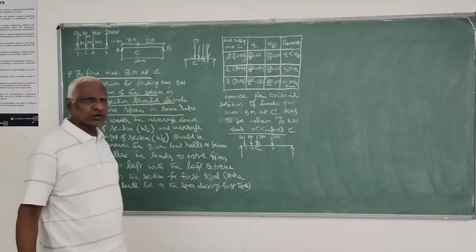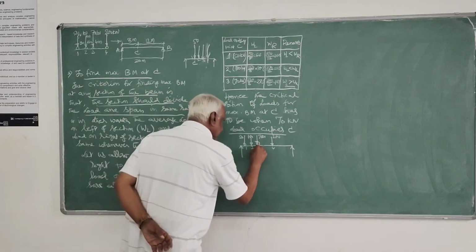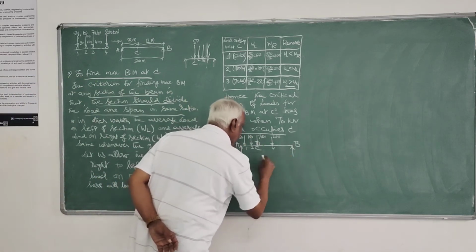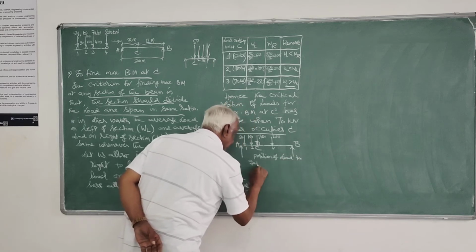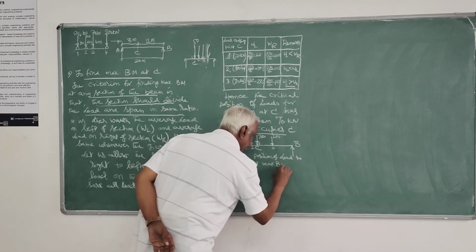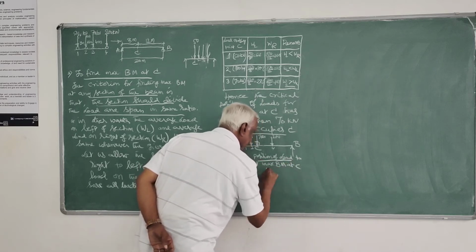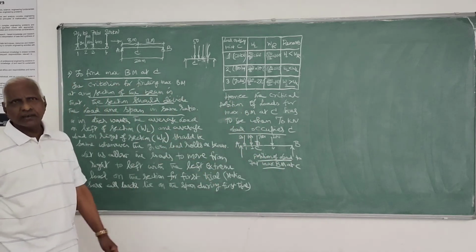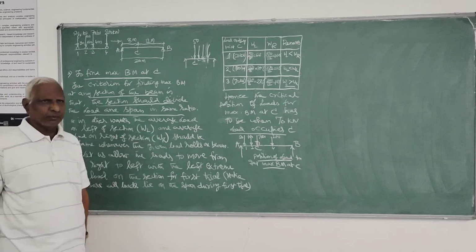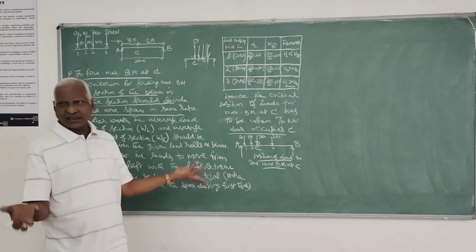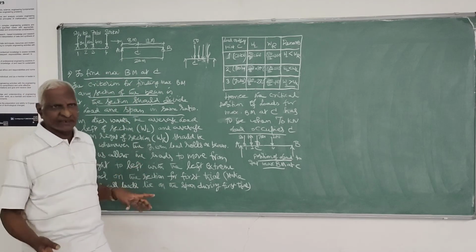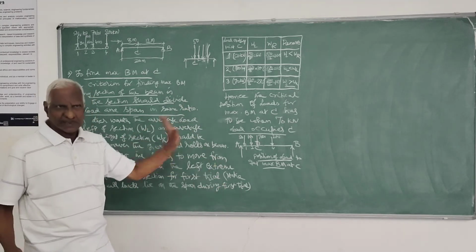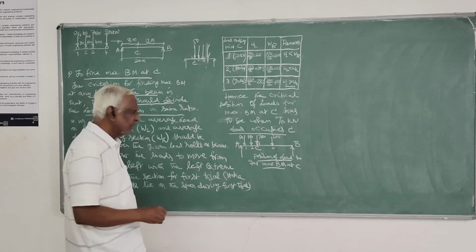This is the fourth load. So this is the position of load to get maximum bending moment at C. Now you use your influence line diagram for finding the moment at the point C. That is your maximum bending moment at the section C. This is what I have dictated. So with the example, I am just explaining. I hope I made the points very clear.